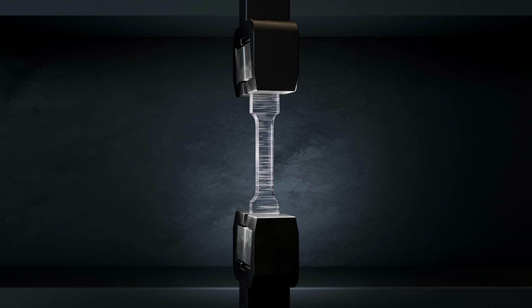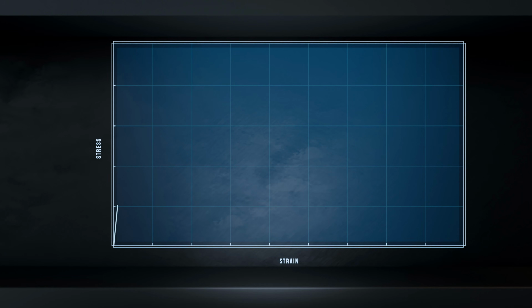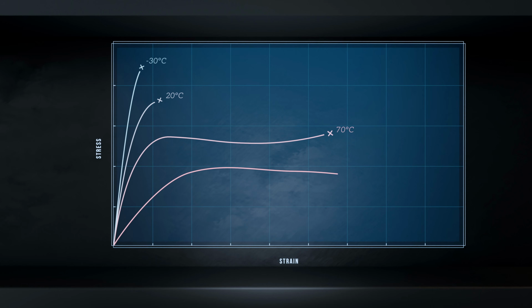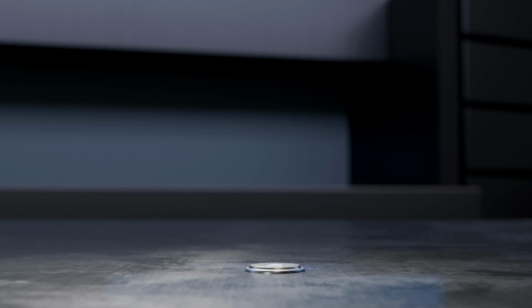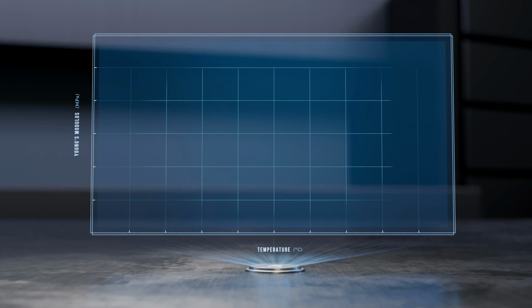Strength, stiffness, and other mechanical properties of polymers can vary a lot with temperature. Polymers tend to be relatively brittle at low temperatures, becoming much more compliant and ductile as temperature increases. Let's look in more detail at how Young's modulus changes with temperature for a typical semi-crystalline thermoplastic. At low temperatures, the material's stiffness is relatively high and stable, but as temperature increases above a certain threshold, it suddenly drops. Keep increasing temperature, and eventually the thermoplastic melts to a liquid, and the stiffness decreases to 0.